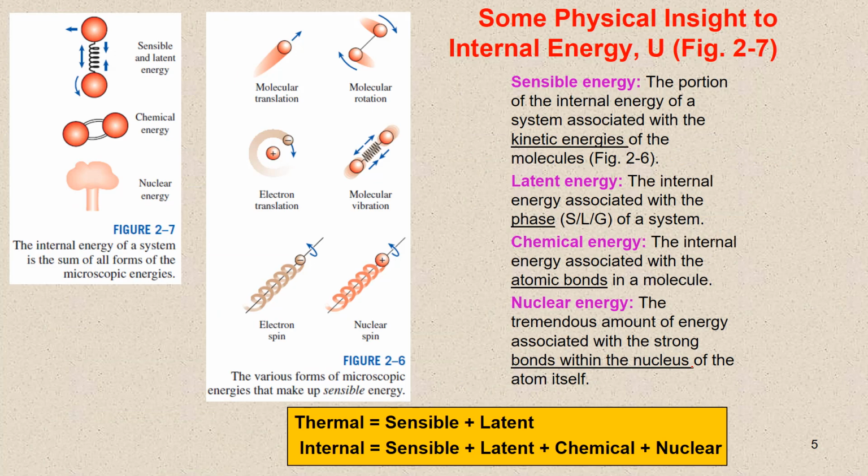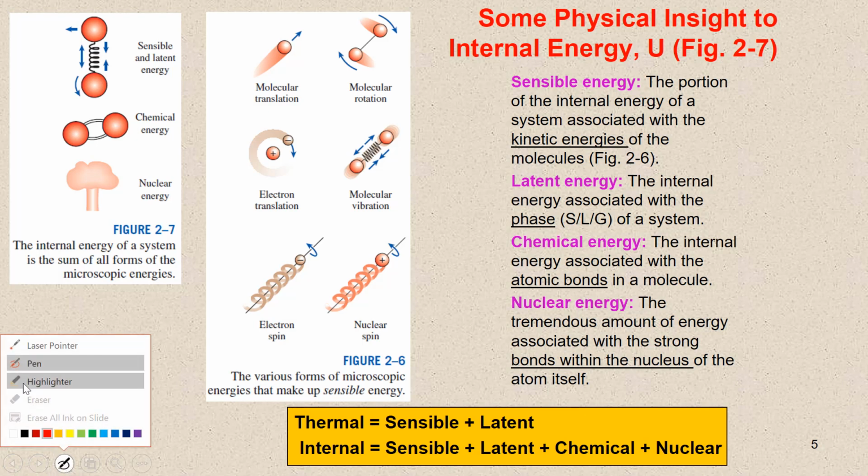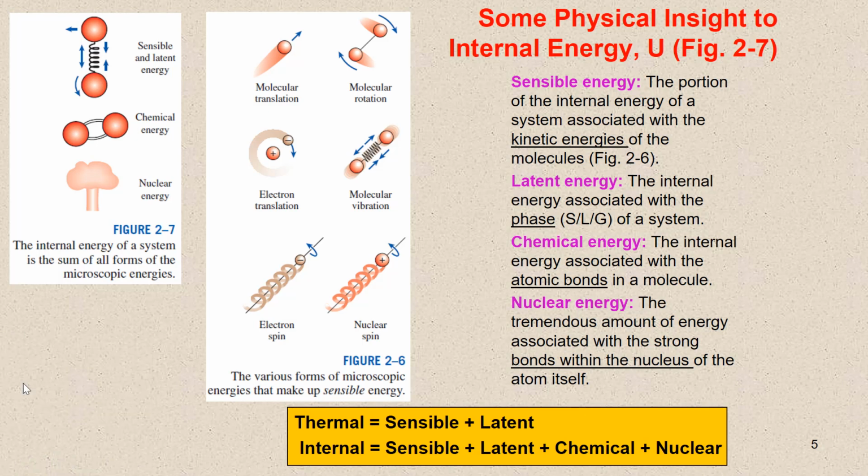Internal energy is defined earlier as the sum of all microscopic forms of energy of a system. It is related to the molecular structure and the degree of molecular activity and can be viewed as the sum of the kinetic and potential energies of the molecules. To have a better understanding of internal energy, let us examine a system at a molecular level. The molecules of a gas move through space with some velocity and thus possess some kinetic energy. This is known as the translational energy.